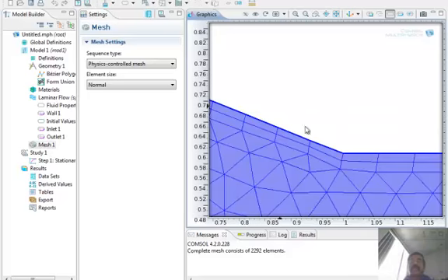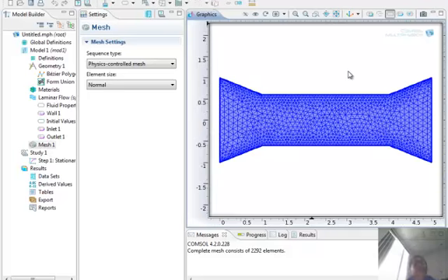Okay, in fact it uses quadrilaterals, rectangles near the boundary and triangles. It puts more points near the boundary than in the middle. Why do you think that is useful? The boundary has the sharpest gradient. The velocity gradient is the largest near the boundary.